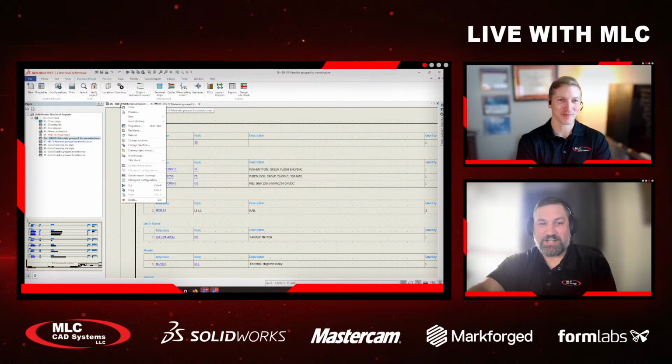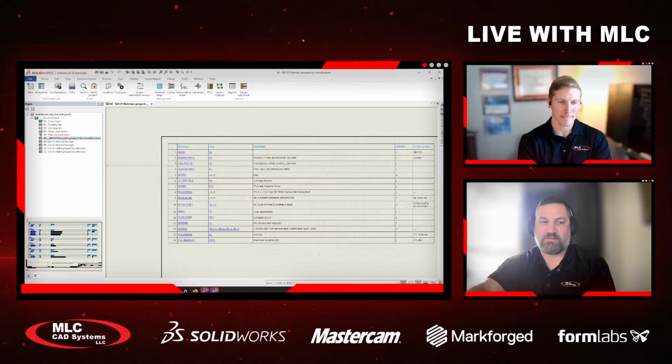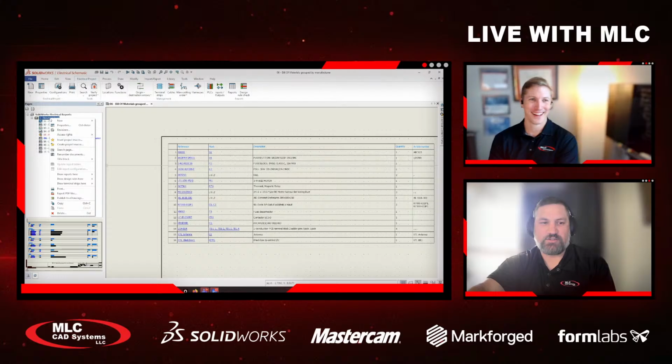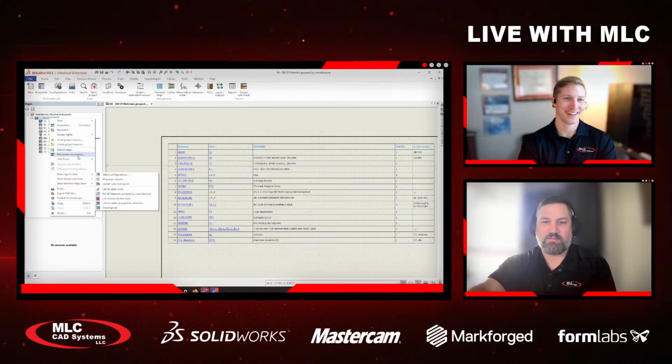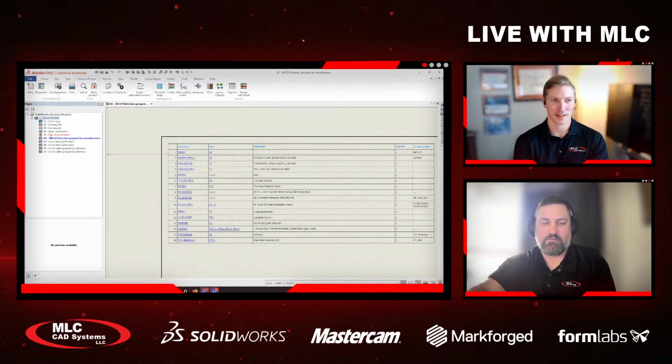Now, once I made that change, again, we have to update the report drawing. Notice that it's page 6 and 7 there, and then now we've skipped 7 and we go to 8. So for the rest of this project, you have to skip number 7. Just kidding. Just right click your book and choose that you want to renumber documents, and then we're going to recalculate everything. We'll hit OK. It says yes, and then now we've reordered everything.